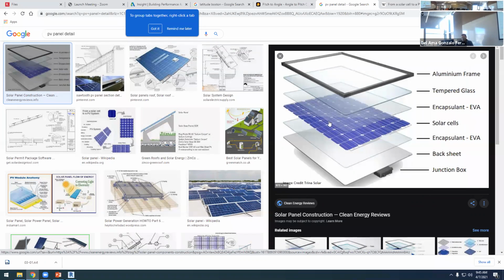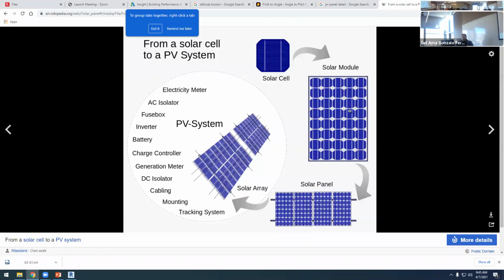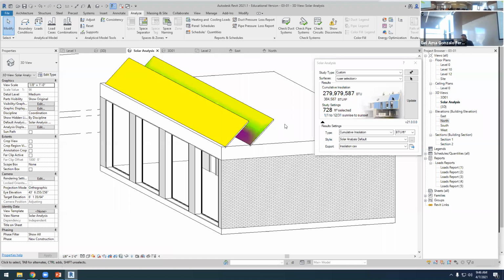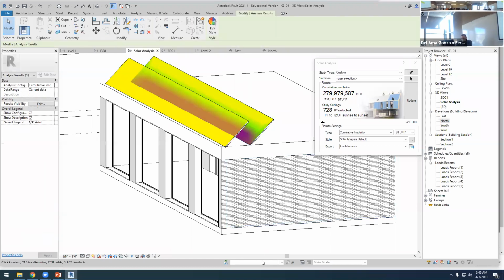If there's a shade somewhere, the flow of electricity is stopped and it doesn't produce any electricity. So that's why those PV panels are very sensitive, and we cannot pretend that, okay, we have a shade here, so only half the panel is working. No, the panel is not working at all. If we have more than 20% of shade on this panel, the panel is not working, or we can assume that it's not working. So that's why doing this is useless. This second line is not working at all.